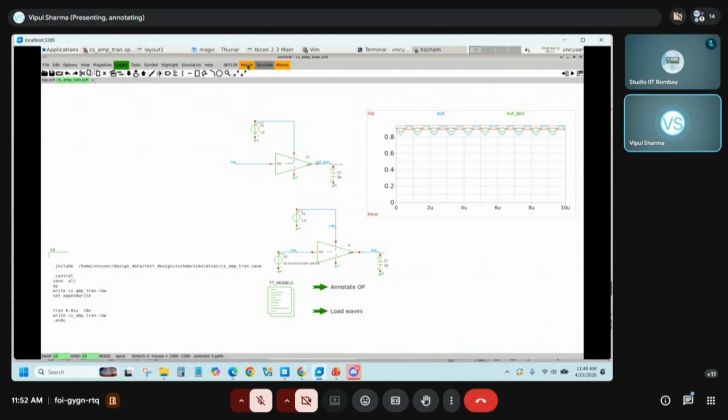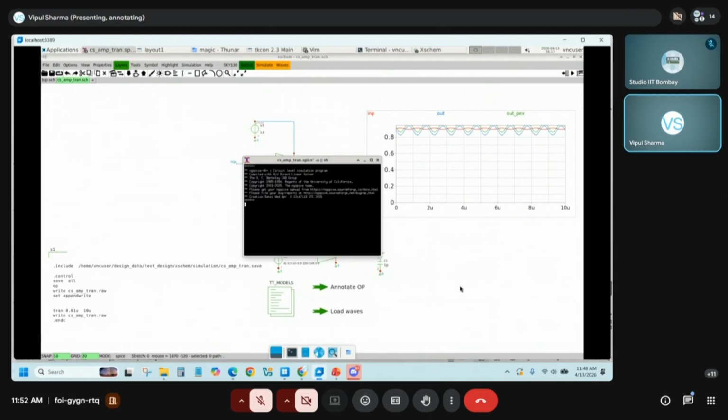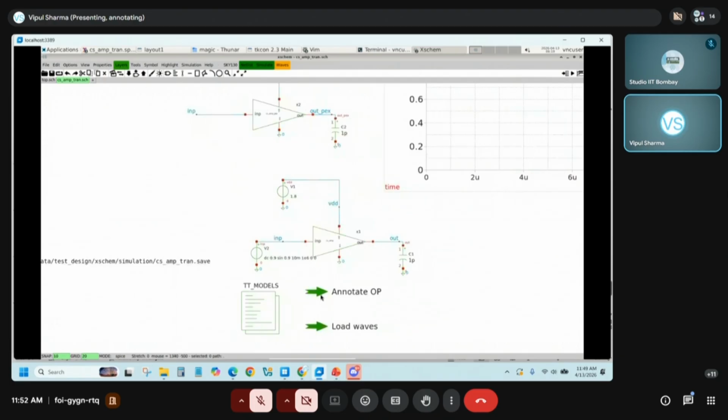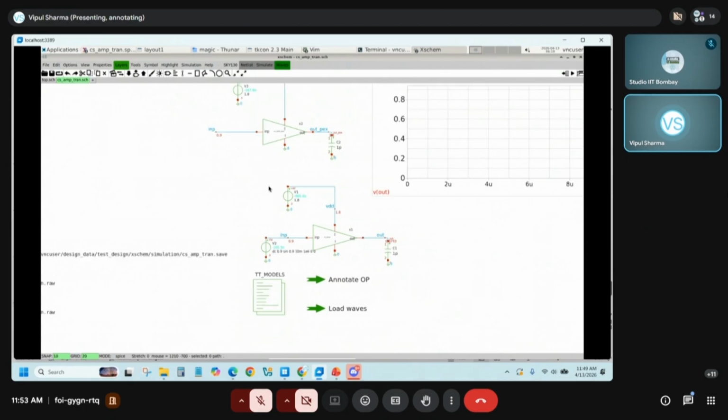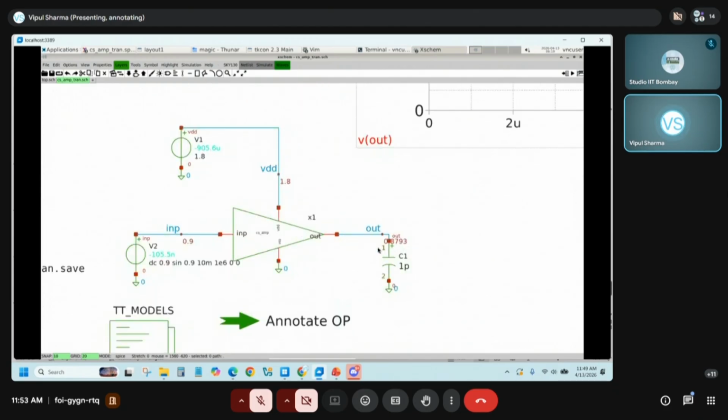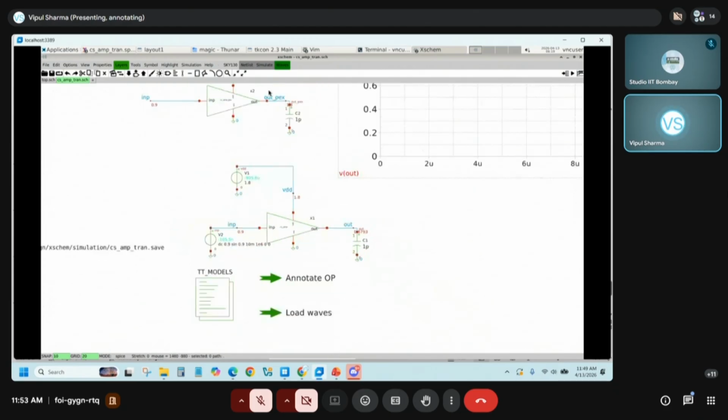So let me run the simulation netlist and simulate. Okay, so the simulation is run. First I will see what my DC operating points are. For that I will press control and left mouse button on this launcher arrow. I think the input VDD and ground voltages will remain the same because they are the same for both circuits. But the voltage of interest is this output. For my ideal schematic, this was 0.87, and for my